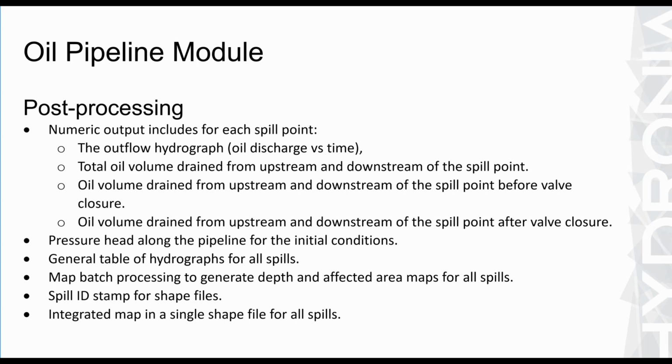So you get a lot of information about how the drain down of the spill occurred. You also get the pressure head along the pipeline for the initial conditions, and general tables for the hydrographs for all spills that are used not only by the model itself, but also to prepare graphs in Excel, for instance.